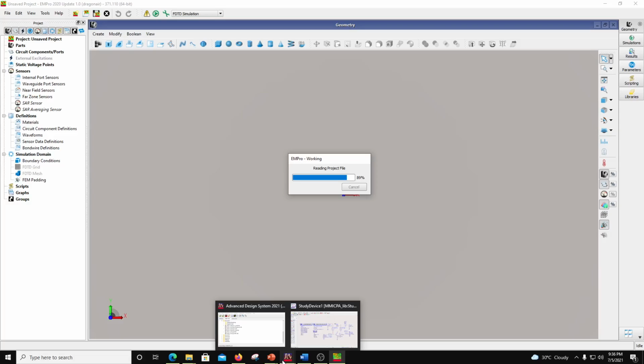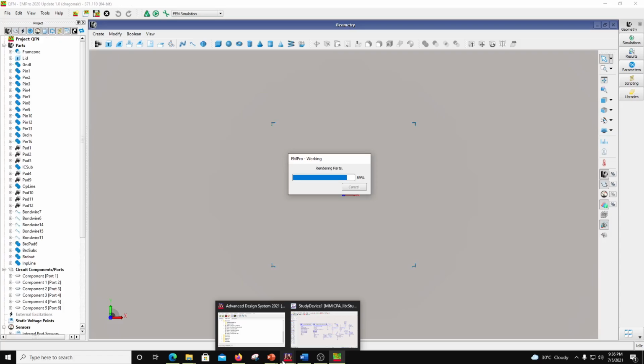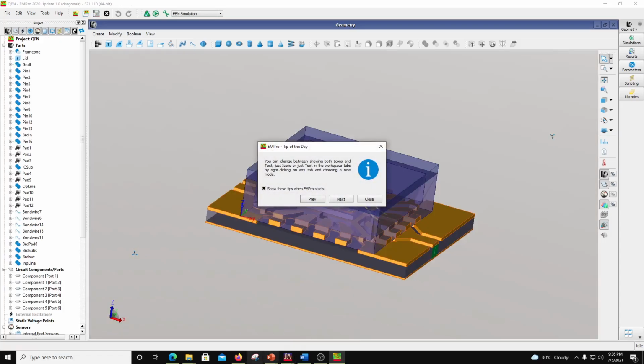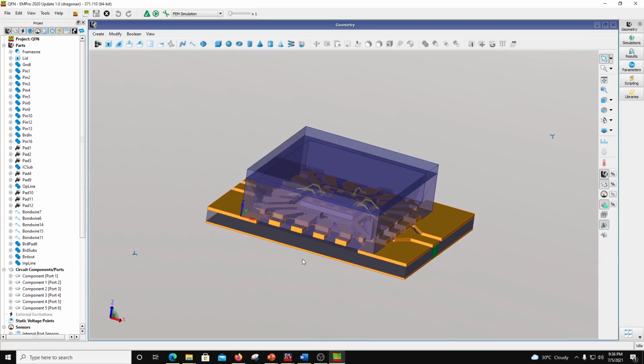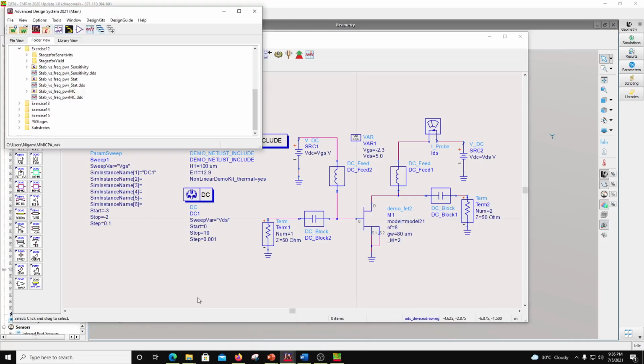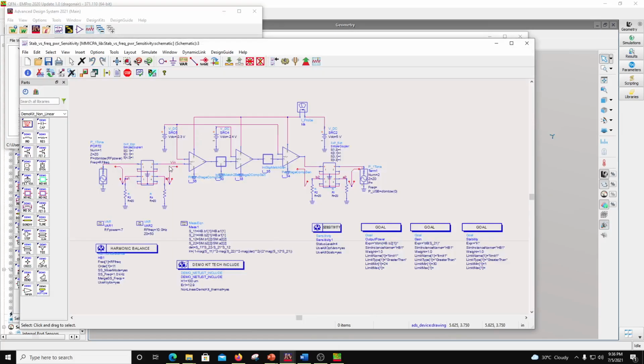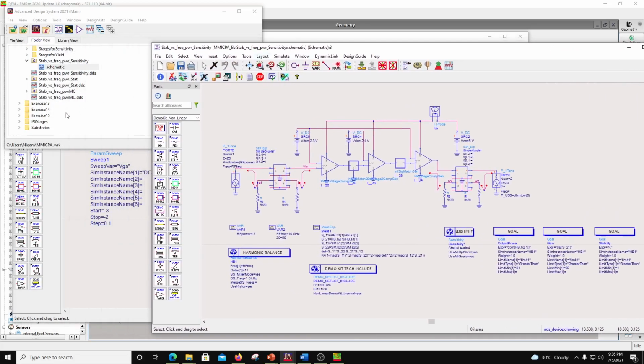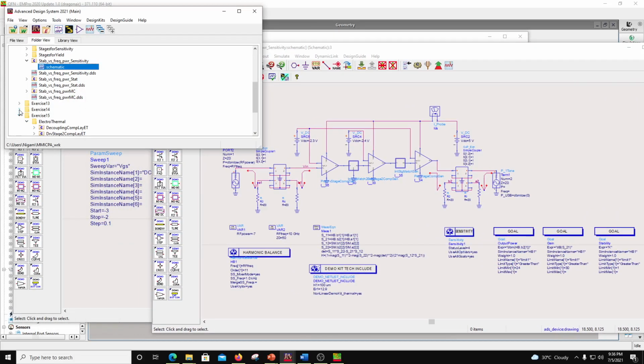So a designer thinks of a package at high frequency first, rather than thinking of the circuit first, because without that you might do a fantastic design over here. Okay, you might do a fantastic design in this sense. Let me show you. Yeah, you can do a fantastic design in this sense, right? But then this might not work. Okay, this might not work unless you involve the package also into the design, right? So the package has to be included in the design, and